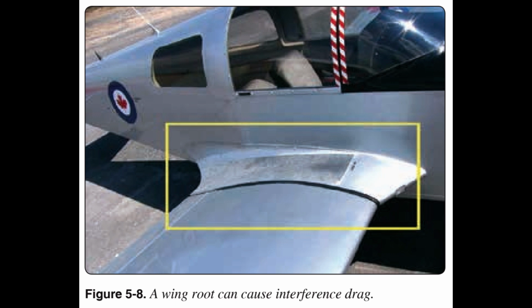If a jet fighter carries two identical wing tanks, the overall drag is greater than the sum of the individual tanks because both of these create and generate interference drag. Fairings and distance between lifting surfaces and external components, such as radar antennas hung from wings, reduce interference drag. Figure 5.8.